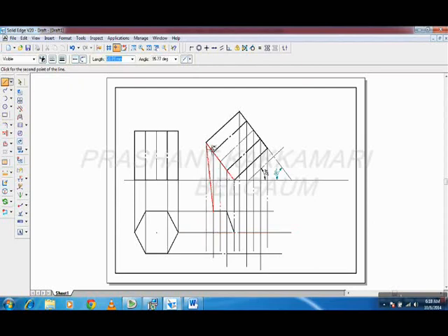And D from this top projection line. So I will click here. D is over. Now this is E. Then F. Again A. So the bottom plane is over, which is hidden, which is visible. You draw it later. So just complete the solid. Later you can imagine from the top and you can draw the hidden and visible lines.